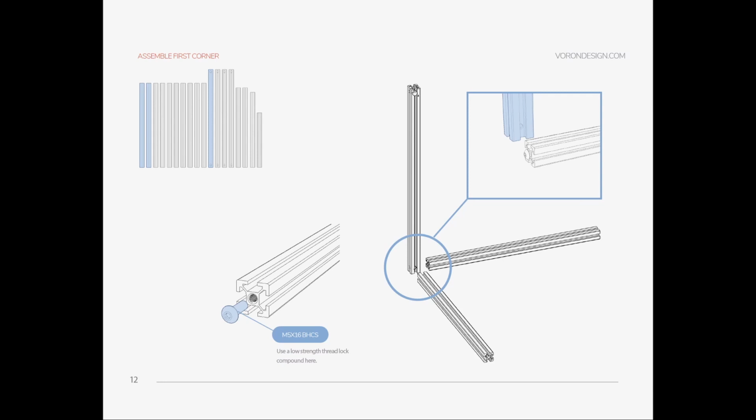This is important because you will tighten this screw while you are putting your Allen key through these holes. So if these are not in the correct place, you will not get a 90-degree square frame, basically. You may drill in the wrong place at first, but you can't move the holes.